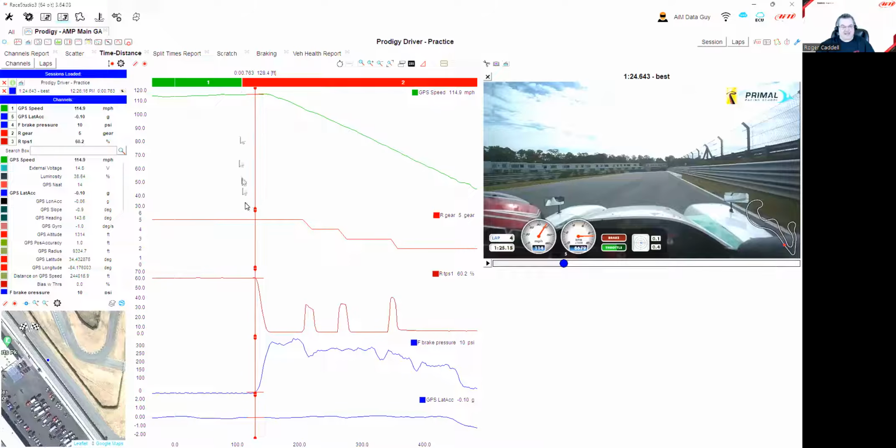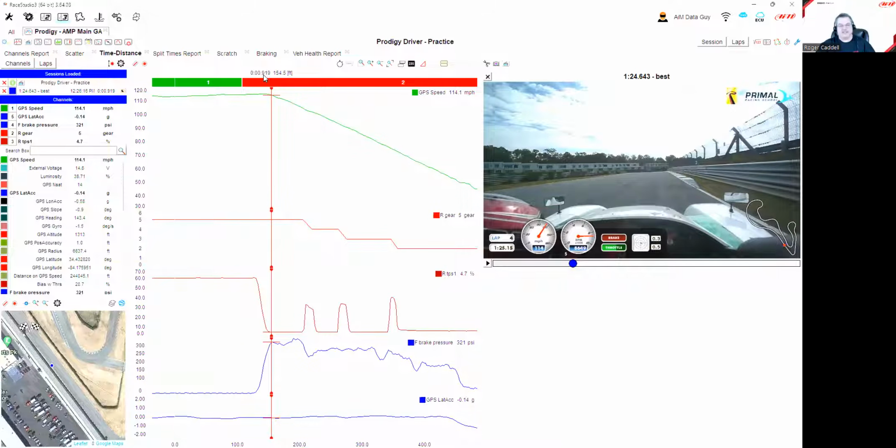So 7/10 past the start finish line, he lifts off the throttle, starts the lifting, and he is at full brake. Again, 76 hundredths, and he is at full braking by 91 hundredths. So less than 2/10 of a second, he has gone from full throttle to full brake. Just something for you as a driver that you should probably understand and make sure that you are doing some of those basics correctly. And just a very quick way of doing that.